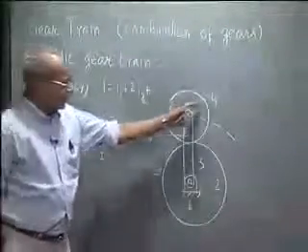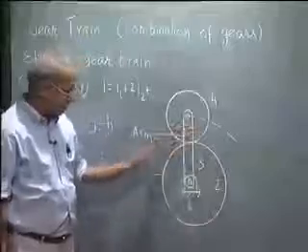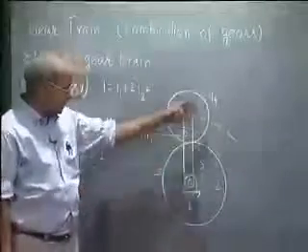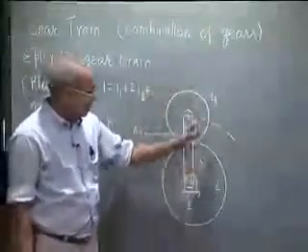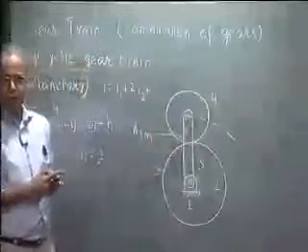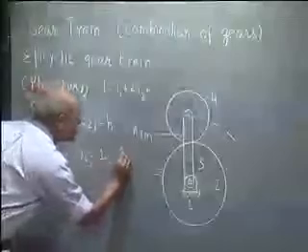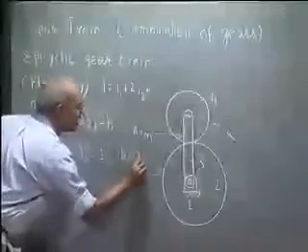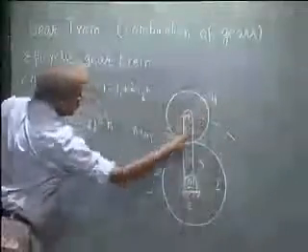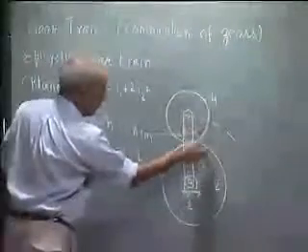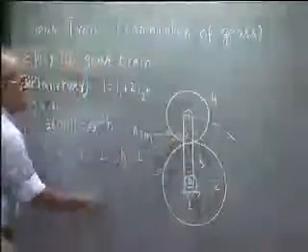And between the gears 3 and 4, these are the pitch circles. Let me not draw, these are imaginary circles representing the gears. Between 3 and 4 we have a gear tooth connection which is a higher pair. So h is 1, and between 2 and 4, gear number 2 and gear number 4 also have a higher pair.